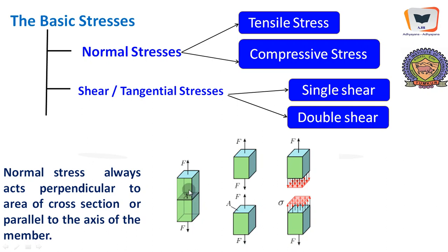We have taken a sectional plane over here and separated it, and we have drawn the free body diagram of part 1, the part above the plane, and the part below the plane, and this is the resisting area of cross section. We can see the stress being developed in mutually opposite directions, and this stress when multiplied by the area will lead to F, and this stress when multiplied by the area will lead to F. Therefore the system is in equilibrium.